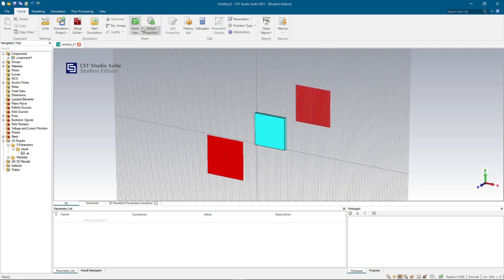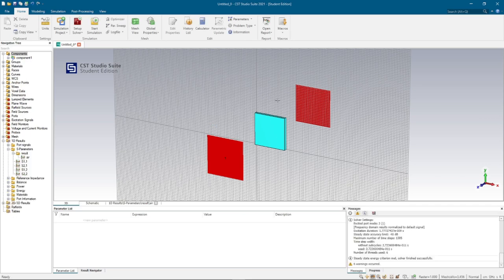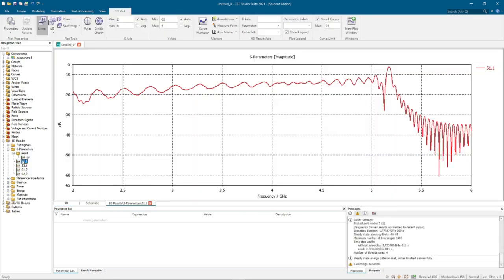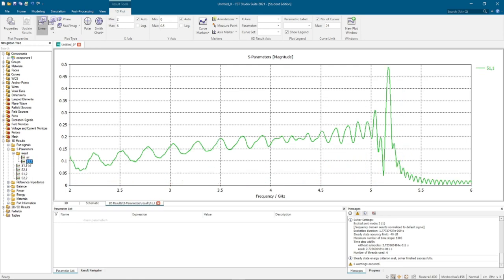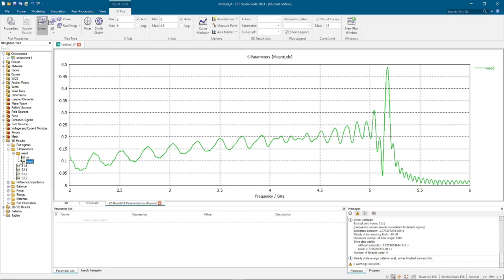So this one, we just run the simulation as the mesh value are still good for us to run. After you run the result, the latest result will be about the wood. So if you want to compare the result, just move the current result, which is the wood one, into the result file, and then rename it as wood. After that, click the file for you to compare the result.